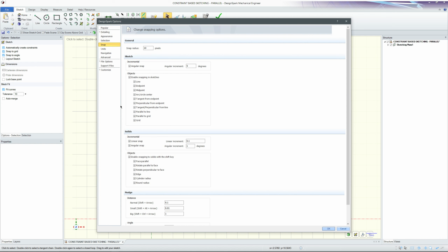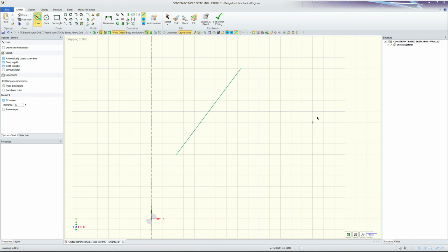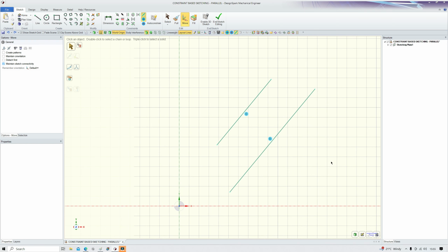When positioning a curve onto a sketch, grid snapping, if set in options, can show and or highlight any set association, allowing a value input and also creating an automatic constraint. In this case, a parallel constraint. Although working in the constraint sketcher, these two curves are not fully constrained, so by box selecting, I can move them, translate, rotate.